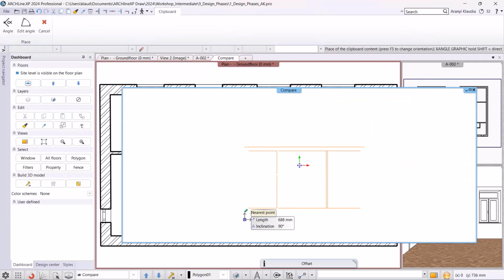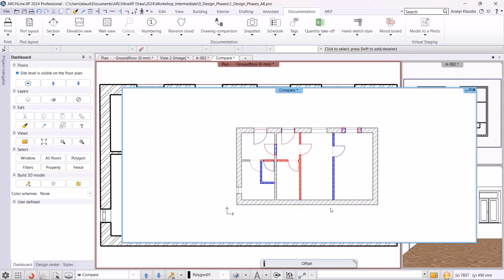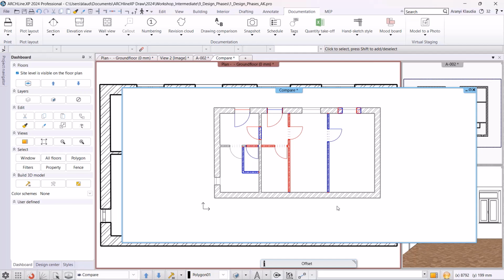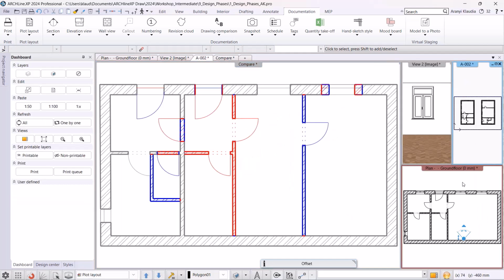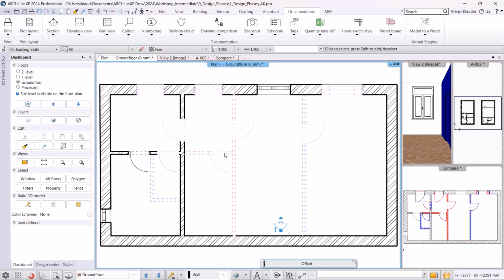This is similar to the all-face filter, but it is a simpler drawing that is created for documentation purposes. It can be placed on the print layout. I go back to the floor plan, and after setting the all-face filter, you can see a similar view. I notice that a door is missing from the floor plan. A sliding door must be placed in place of the demolished door.